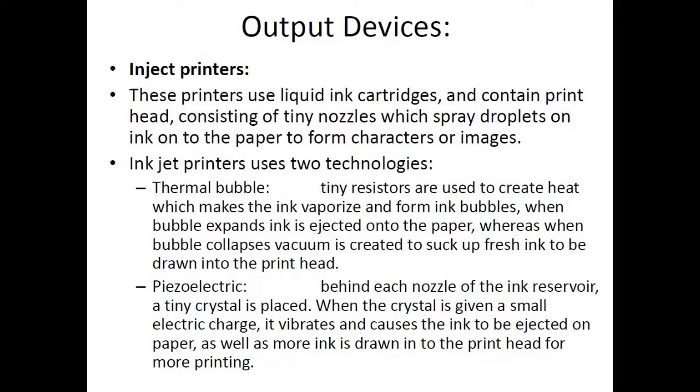And piezoelectric: behind each nozzle of the ink reservoir, a tiny crystal is placed. When the crystal is given a small electric charge, it vibrates and causes the ink to be ejected onto the paper, as well as more ink is drawn into the printhead for more printing.